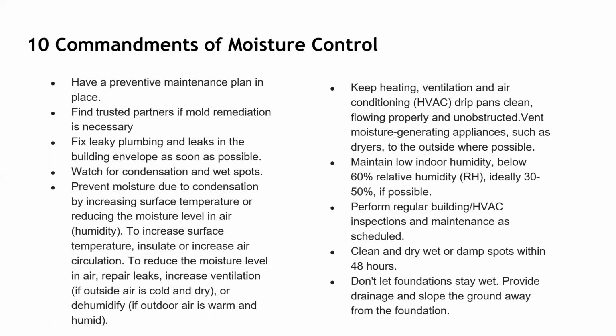And also think about your foundations. A lot of our buildings in Southwest PA are pretty old, and with time, sometimes they'll sink, sometimes the foundations will change. So you need to do a walkthrough to take a look at whether water can be entering through the building envelope in that way.